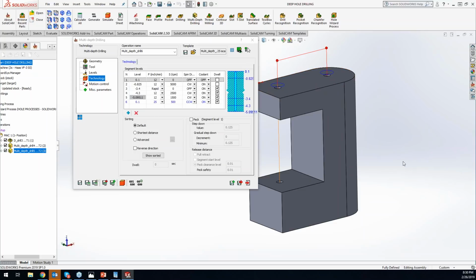And I would think too, with a long tool like that, Kevin, that was kind of my thought too. Yep, a lot of flex and a lot of chatter if we're doing a circular interpolation, especially on a 5-inch long mill, if we don't break it. It's kind of what I was thinking. Yep. And like I said, think of this, guys, as your own custom drilling pattern, because I don't want to say cycle, because it's not a cycle that's built into your machine.